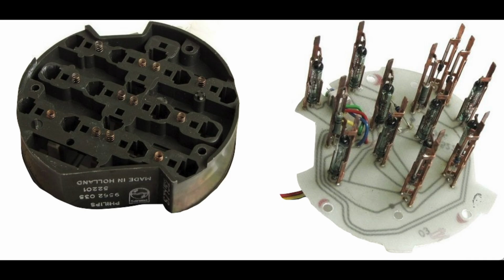The keypads of the early Philips push-button telephones had a complex arrangement of switches. In my matrix version of the GDK1 keypad, the switching is done with reed relays. The levers connected to the keys hold miniature magnets. These levers with magnets activate the reed relays for some keys more than once simultaneously.